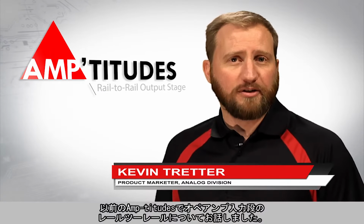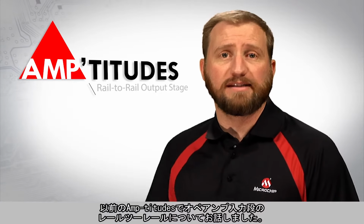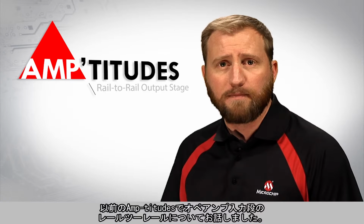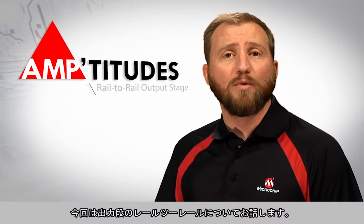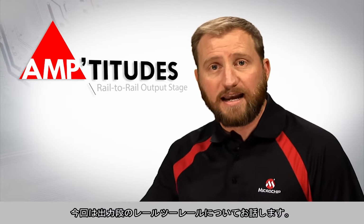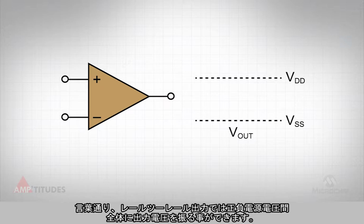In a previous Amplitudes series, we explored the term rail-to-rail as it applies to the input stage of an operational amplifier. This episode will focus on the same concept, but as the term rail-to-rail applies to the output stage of an amplifier. Now, as the name implies, rail-to-rail output indicates that the output voltage range of the amplifier can span one supply rail to the other.